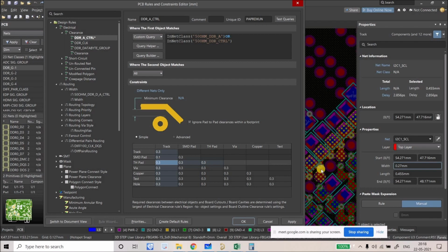There is another small size of via that we're going to use for signals, but again there will not be much difference from the vias we are using for power supply. So from here I got to know, okay, 0.1 mm, or you can say around 6 mil. This is the clearance that is enough for this one, and it is manufacturable. So this is not just a guess, right? This is a properly analyzed exception we are putting here.